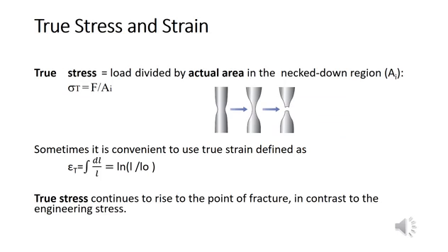And then we have the concept of true stress and true strain. Previously, in the engineering stress, we assumed that A remains constant, which is not true as shown in the diagram. So true stress becomes the force over the actual area. The same thing with the strain, it becomes a change of length over the actual length, which when integrated we get that.